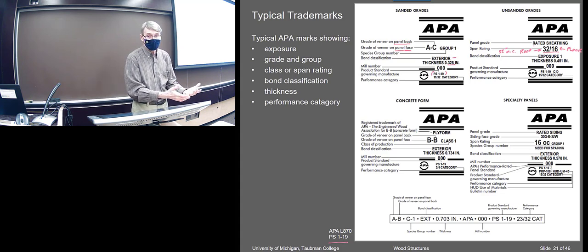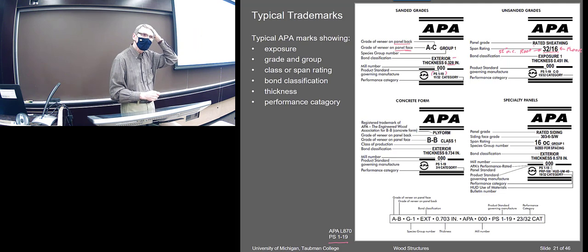Actually, I think it's higher than that, but whatever. They pick, and then they give the on-center spacing for the joists it would carry, and it carries it not just in flexure but also deflection. We can see in the tables they give different deflection limits, like 360 or 240 or something like that. Probably over 180 for the roofs.